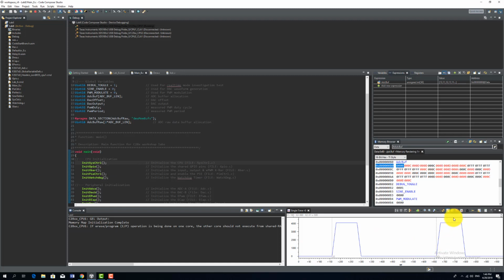And if we want to get the continuous response of our signal here, we can easily click this one, the continuous refresh, and as you notice, the value will start to change. The same with your ADC buff. To ensure that the system is running, you can also verify using your LaunchPad. The LED D9 should be blinking on your LaunchPad. And this is how we run the DMA, how we convert digital signals into their equivalent analog, or digital to analog, vice versa, without processing by the CPU. All we need here is the DMA controller to facilitate the whole process.